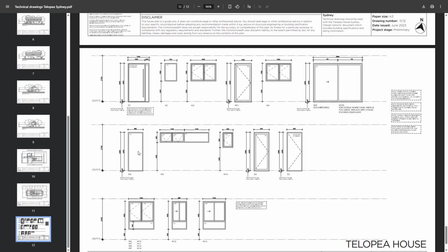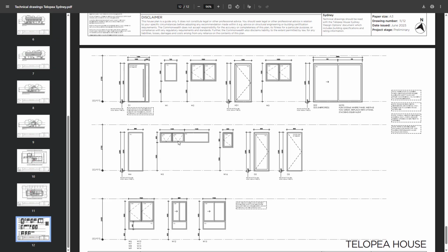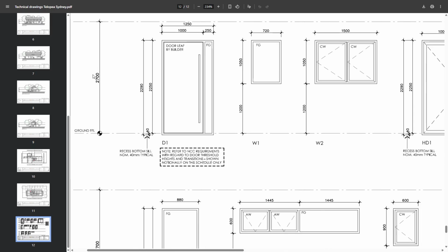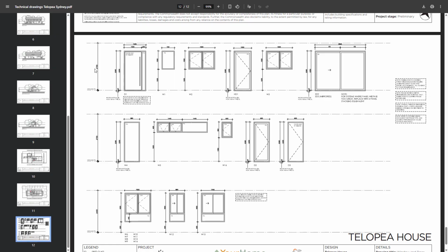And if you're lucky enough, you're going to have a set of window and door schedules, and you're going to want to use these moving forward, because this really tells you, particularly from a geometry perspective, that you've got lots of common details here. Actually, it also gives me an indication that my assumption on the floor-to-floor height, I might want to adjust that to 2700, because that's probably the better indication of the actual condition space.